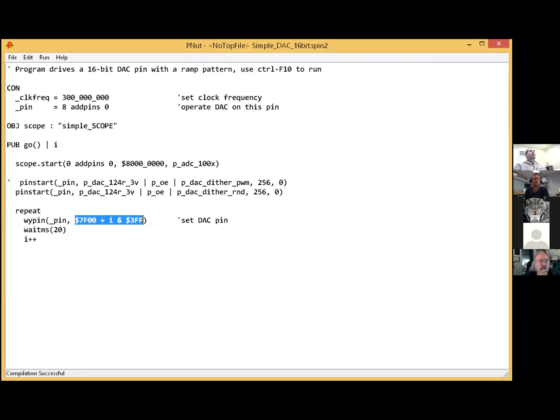So we have this thing set up for super high magnification. At that point, we need to be midpoint output because the ADC at 100x magnification wants to see a signal that's near the middle of its range, and it will resolve it. So what we have here is this value 7F00. Remember, that can go all the way to FF00, right? But at 7F00, we're midpoint. So we're in the sweet spot of where the ADC can actually read it.